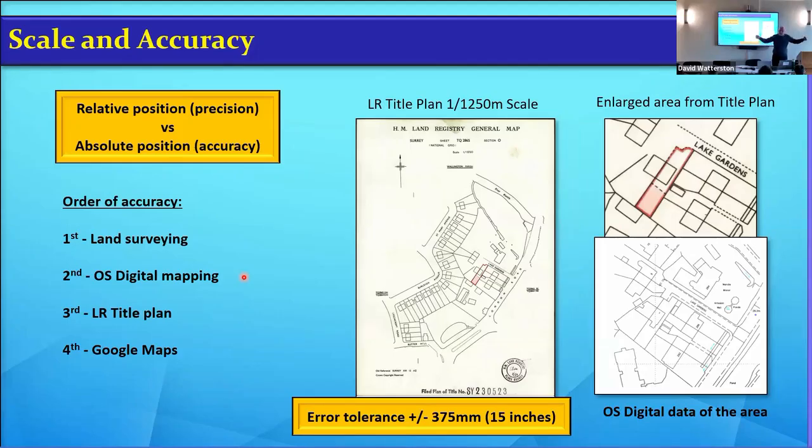But it means that you can then move one of the boundaries in, right? But you don't know which one. So then you measure from the house to the boundary at this side and the house to the boundary at that side and find out which one's best. And then start your preliminary drawing by correcting that line work from the Ordnance Survey.